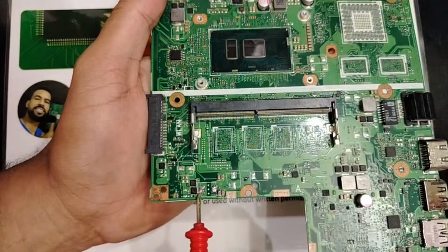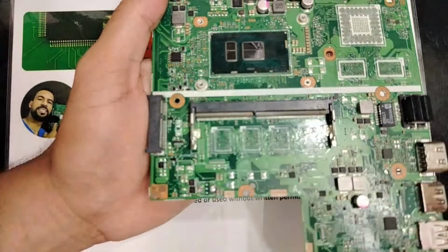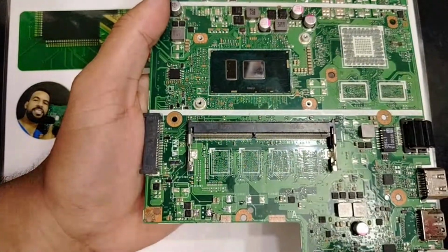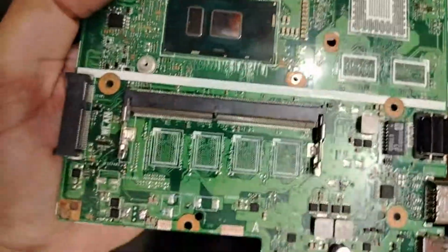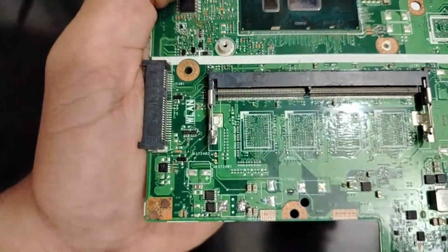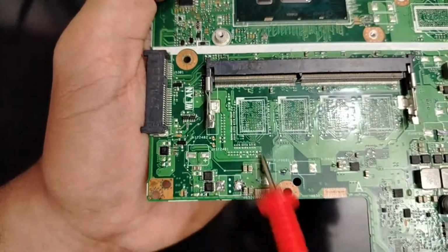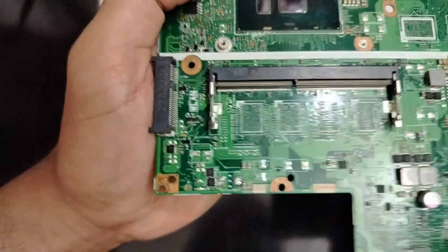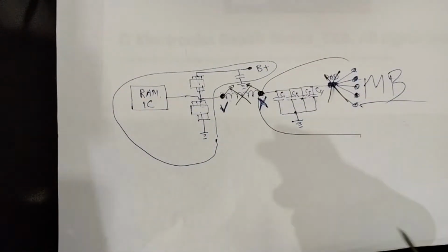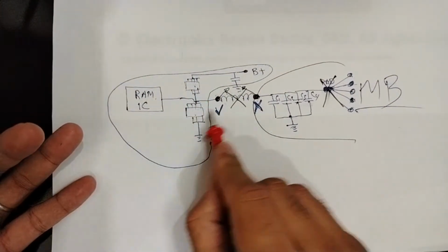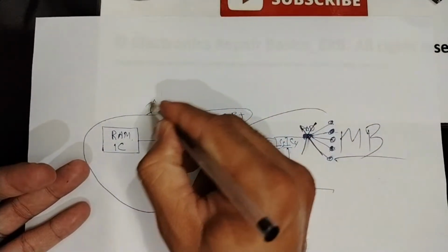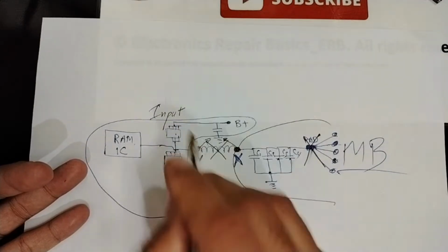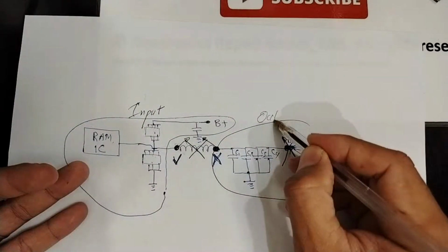we were troubleshooting the short circuit before, very fast. Now I will remove this pad here. Okay, let's zoom like this in order to make the board easy. Guys, we have a shorted circuit. I told you that the basic circuit is this one. Always you will find the IC, MOSFETs, coil, ICs. This is the input, my friends. Here we have the input, basically. Okay, here we have the output.